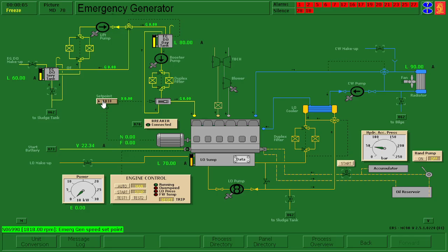This system here is able to regulate the speed of the generator. That matters in AC systems. As you know, well, you probably don't know, but the speed of the generator is what makes the frequency, not what makes the power output, right? So when you're synchronized, the power output is generated by Faraday's law or Lenz's law.